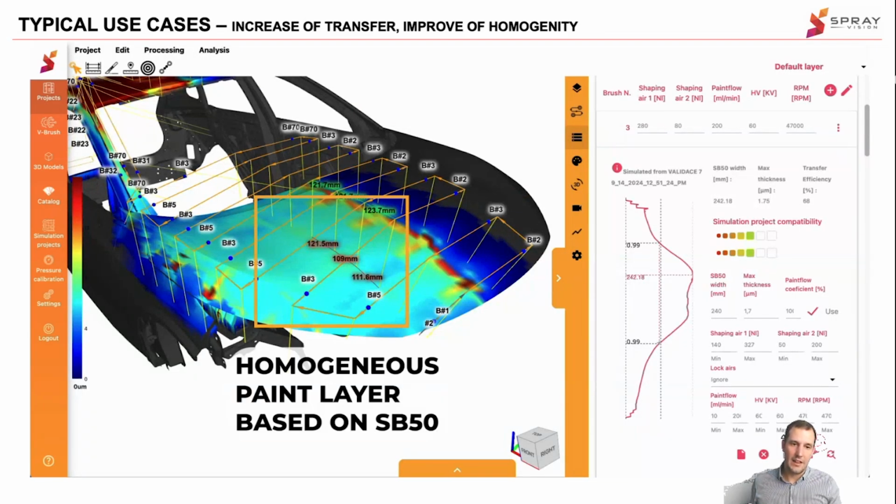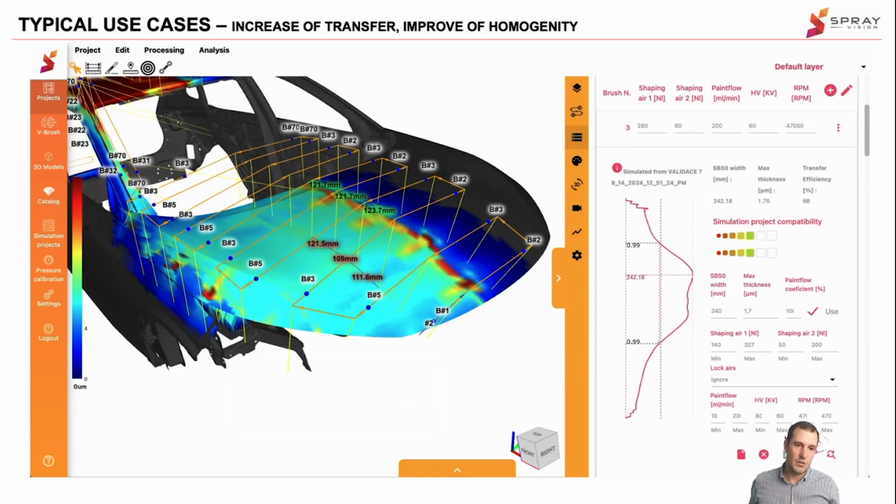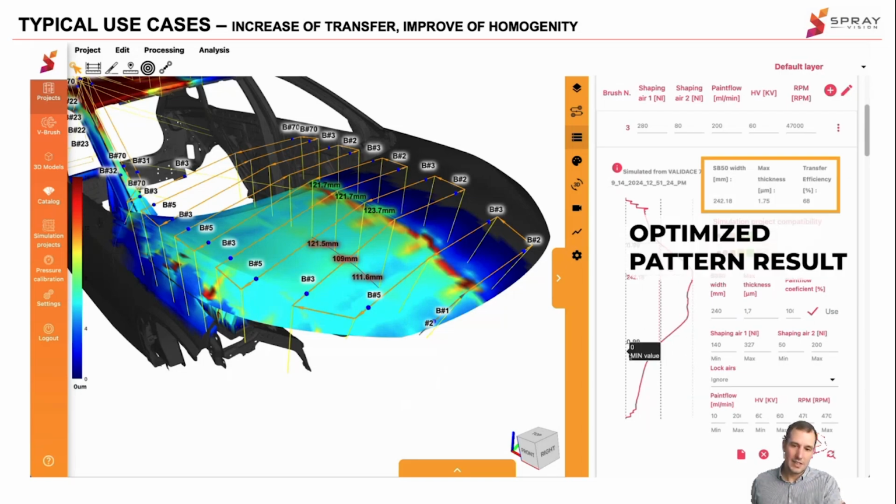Again, it delivers the spray parameters which you should use, and you see that the output is much more uniform. So the uniformity significantly increased, and you have a much more uniform pattern and spray output to deliver homogeneous application, to which, for example, metallic paints might be sensitive. It also has the big advantage that you are able to have much better color matching through the whole surface.